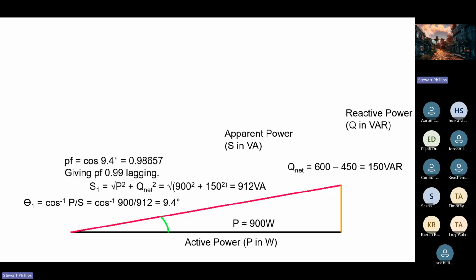There is quite a bit of danger in these capacitor banks, though, as they click in and out because they hold a lot of charge. When they're clicked out, if they're not fitted with a proper discharge path, they can sit there holding their charge for months. There have been reports of people coming across capacitors that have been disconnected and sitting on a shelf, and they've tested them for voltage, and they've still held the charge after several years. So it's always good to be careful around capacitors, especially the power factor correcting ones, because they're usually quite big capacitors.